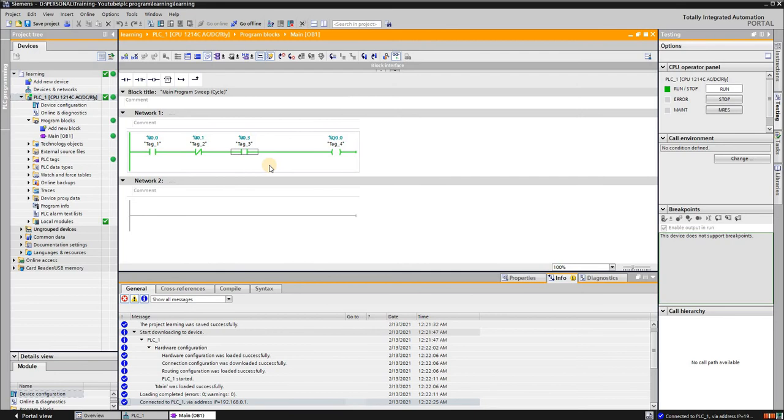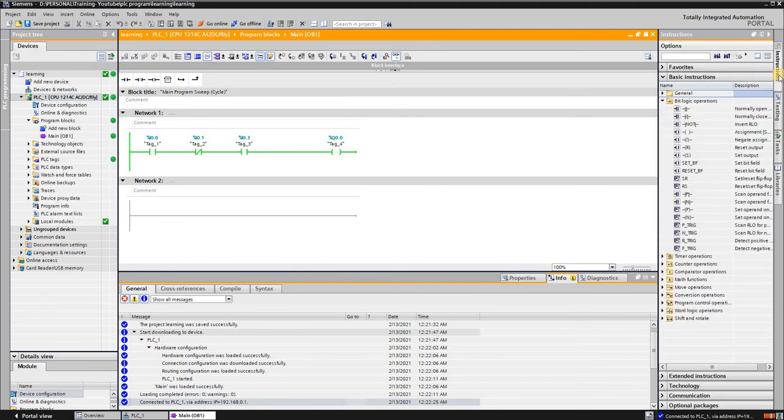And definitely for a process, you don't want your motor to be controlled only by level switches. Maybe there are sudden fluctuations in that. So to avoid rapid turning on and off of the motor, the real process is something different. We need a timer block to make sure the motor is running a minimum time. So you can find the timer blocks. Maybe when the level is high, you want to make sure the motor is running for at least 10 seconds or 15 seconds.